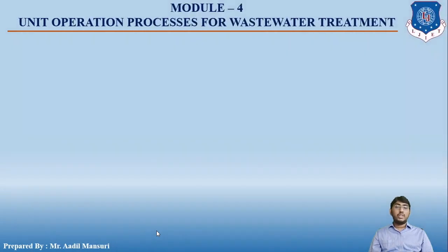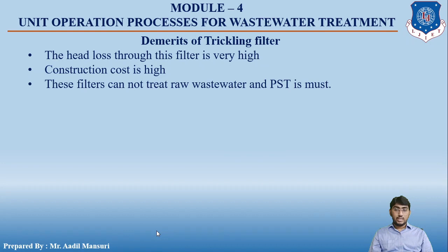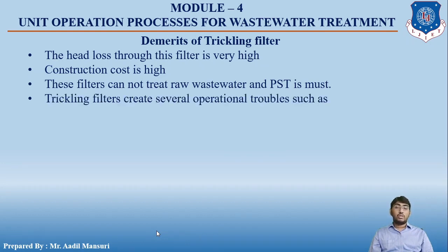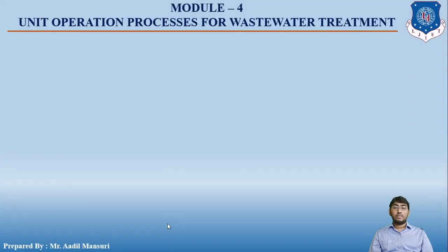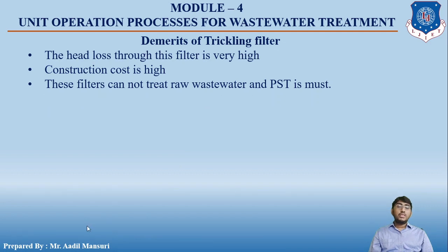Let us talk about the demerits of the trickling filter. The first one is that the head loss through this filter is very high. Construction cost is high. Then these filters cannot treat raw wastewater, and a primary sedimentation tank is a must.